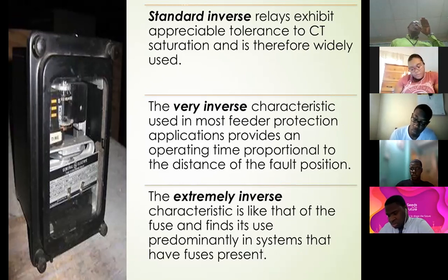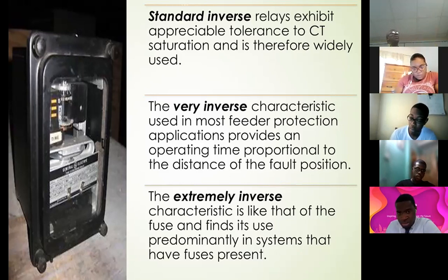So as you go along that feeder, what you're doing is moving further and further away from the source. You see? And if you're moving away from the source, then it means that you're going to have increased resistance, and therefore the current flow will change. And also the fault current that you're going to experience along the feeder will change as you move away from the source.